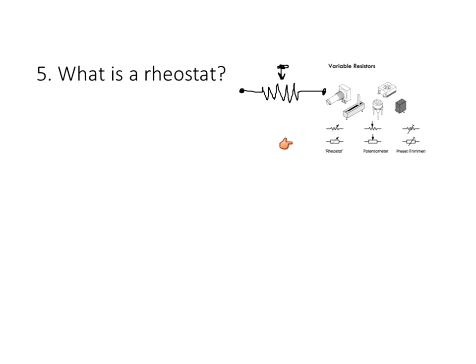Okay? Now, there's different ways to wire these. If I use all 3 terminals separately to separate parts of a circuit where none of these are connected together, they just simply call it a potentiometer or a variable voltage divider because you're using all three terminals. You essentially are splitting this up in here into two different resistances. Another way to wire this, though, is to actually tie this wiper to one side of this potentiometer. And when you do that, you actually end up with just a pure variable resistor.